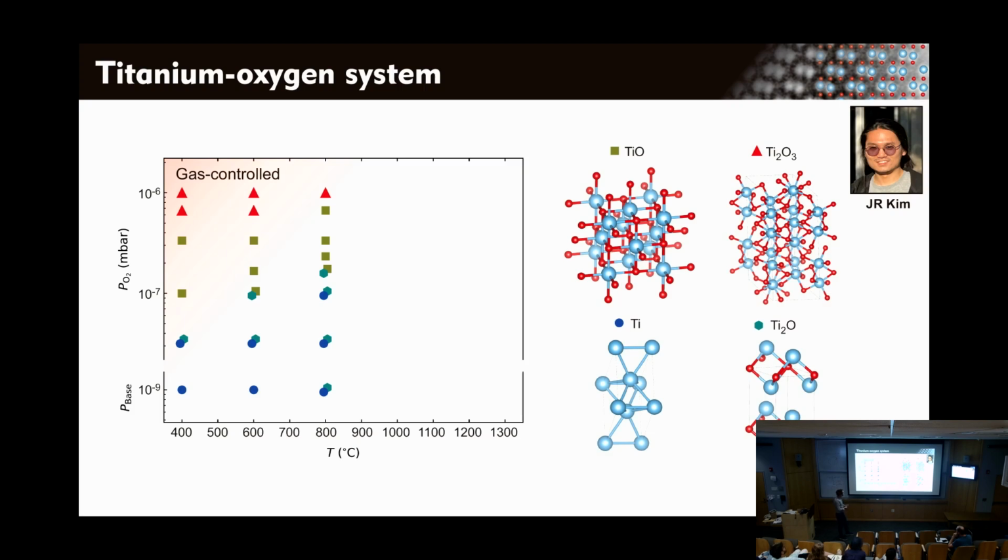Okay. So I'm going to try to replicate an Ellingham diagram over here experimentally. And I can illustrate that by staying at low temperature, for example, and then increasing the oxygen gas that I inject into my chamber. And I can see that I go from titanium metal to TiO to Ti2O3, which is exactly what you expect. Right? You're increasing oxidation by injecting oxygen. Fine. So this is gas control, this is conventional.